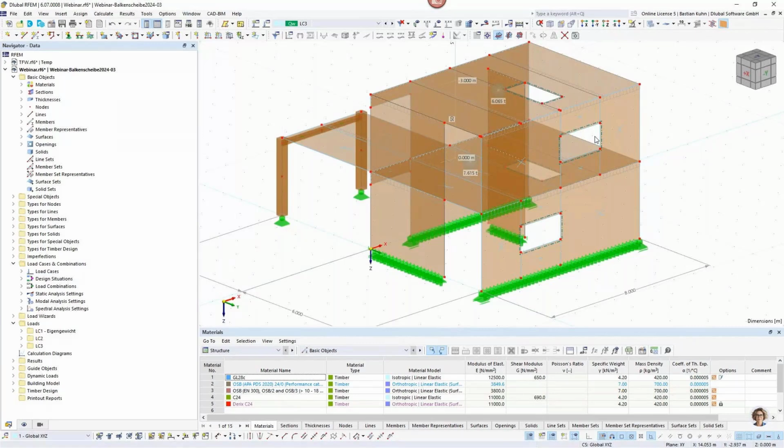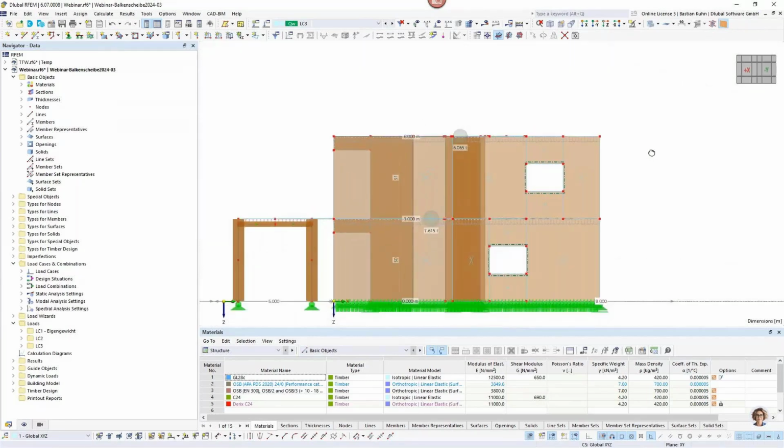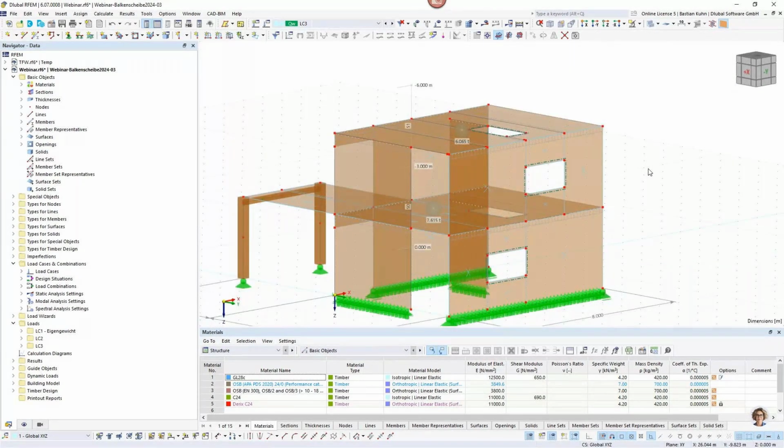And this is for a hand calculation. And what would you do when you calculate such a structure by hand? You would calculate your horizontal force, and then you would say, okay, this surface cell will bear this horizontal force, and this surface cell this, and I need anchors here and here on this point, and I'm totally skipping the elements in here.